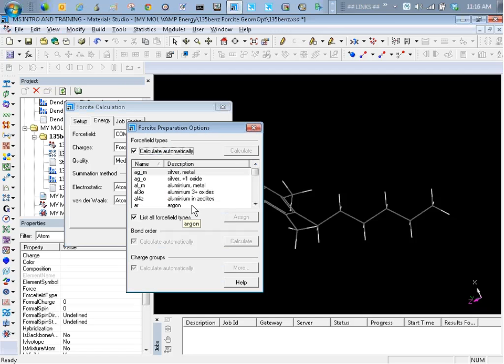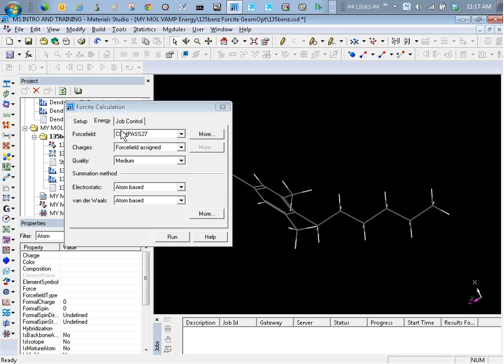What's also important is, within the force field, I can actually look at the atom types. So we all know in the molecular mechanics sense, if you are a molecular mechanics person, that there are different force field types, and sometimes you want to investigate or reassign atom types. Material Studio has an atom typing engine: it sees a set of atoms and you call a force field. It says what atom types are available. These are what I know about the connectivity, topology, and hybridization of those. Therefore, I assign these atom types to them. All right. So you can go in and see all those atom types, and you can show only the ones that are relevant to that structure, or you can list every single one in the force field. There are different options there. You can change those, right?